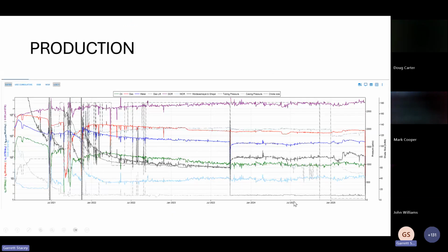So here's a more precise set of production for our well. One of the interesting things about our well is we started to have real severe issues with scaling with our gas lift. We were historically doing single point high pressure gas lift with annular flow, and we started to have real issues with scale, and we're scaling tubing in the well bore and unable to get those out, and we're losing well bores. And so we switched almost all of our wells from annular flow to tubular flow, which cost us some production in the short run, but we haven't lost any well bores since then.